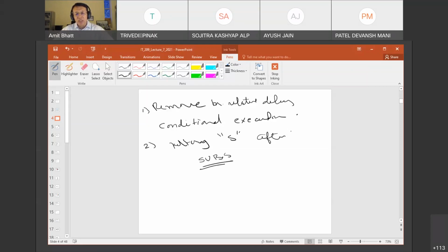For that, you have to do the subtract operation and then use a compare operation on that register. If the answer is 0, then the zero flag, or Z flag, will be set. But here, if you do this, it would give you the result, and if the result is 0, the zero flag will automatically be set. So these are the two ISA-based techniques which we studied.